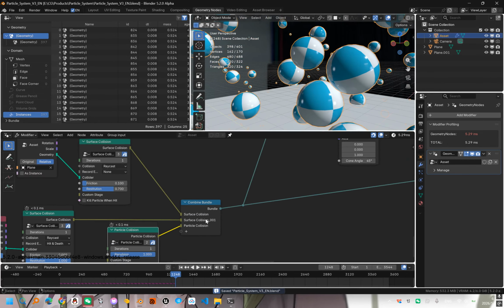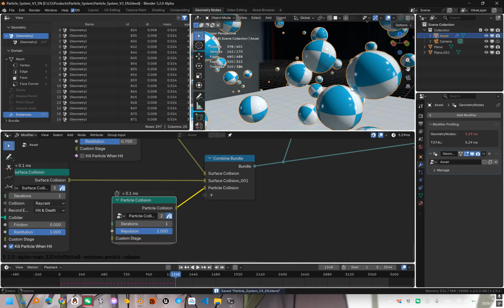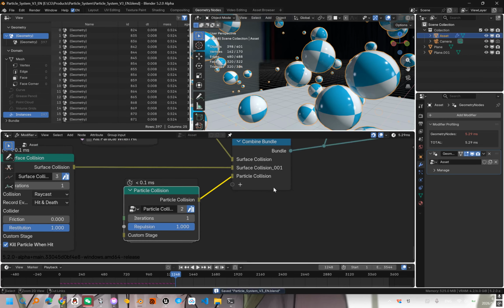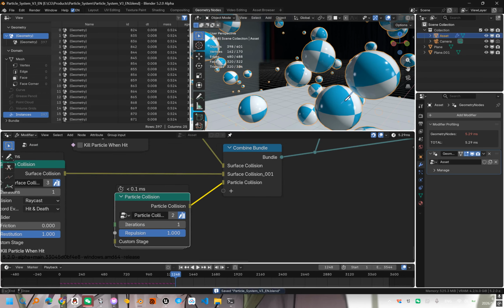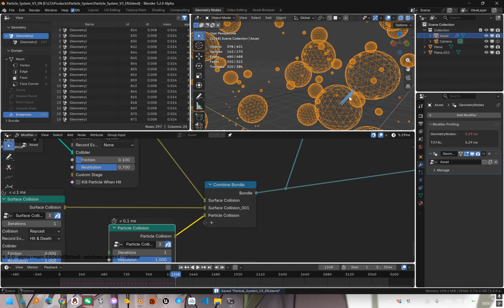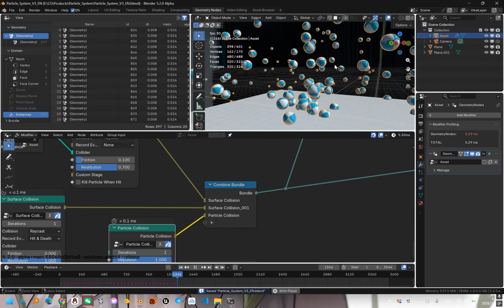Because the delta time is very small and here you're still pushing the particles away from each other, it will suddenly have a very large repulsion to push the points away from each other and push them outside of this sphere. Because this distance is the same, you just push this distance, but the delta time is very small, so that force will be very large, and that gives you a very large velocity.